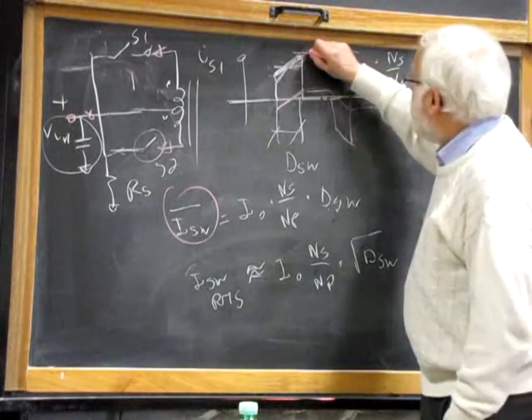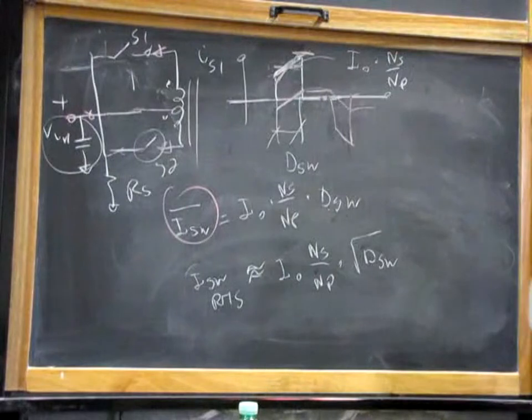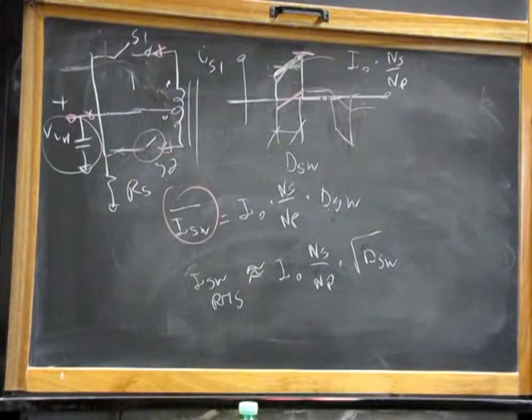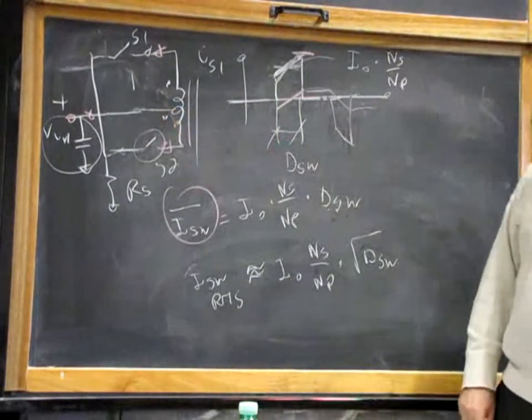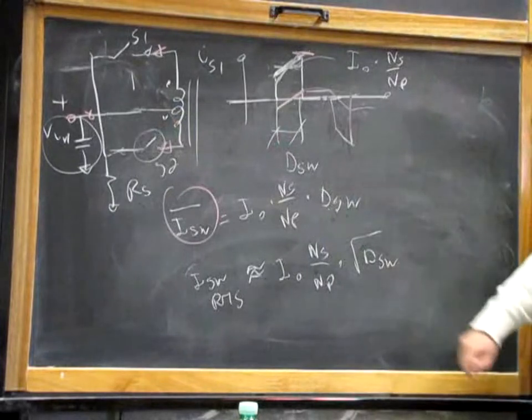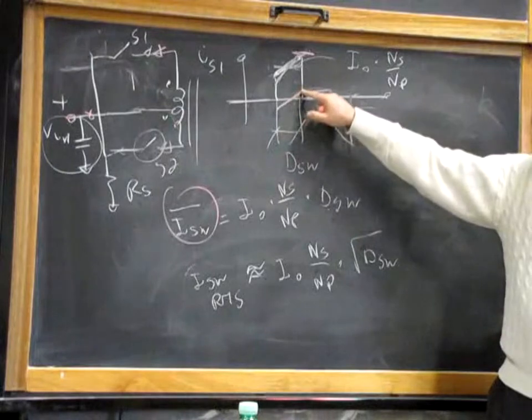What about this peak value? Peak value is equal to the output peak current to the inductor, and you know how to find the ripple on the other side, moved to the primary side via some ratio. And if you want to be very precise, you can also add 1/2 of the magnetizing current.